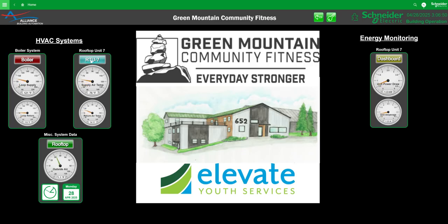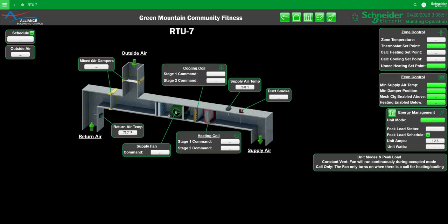Then also there's rooftop number 7, and again, the thermostat set point is here. Now, I thought it would be locally controlled by the occupant, but I'll have to check on that. Maybe this allows you to override it. And this is your night setback set point.